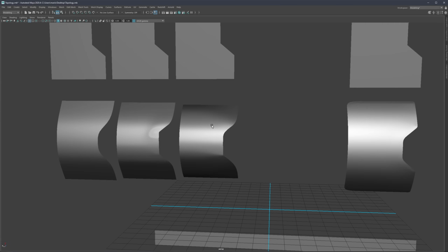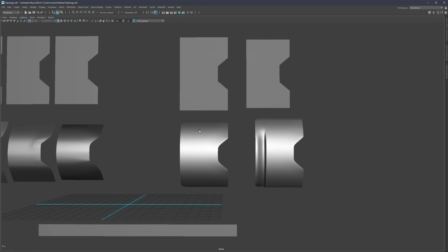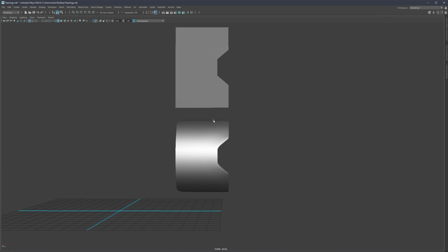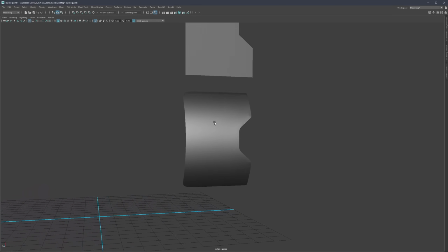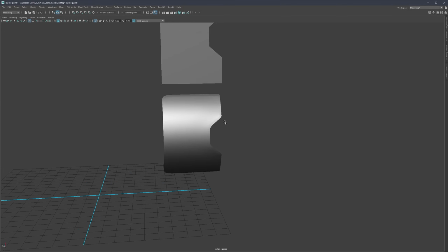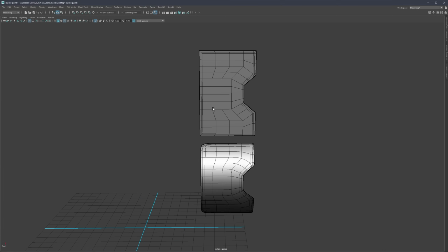So we can also think about how we can use all of what we learned from these mistakes to our advantage and create much more optimal topology, as shown here. Here we can see that the highlights are very, very stable, the corners are still relatively sharp, and we do not have any deformation. The important things to take away from this are three things: supportive loops, even spread, and redirection. These three key elements are something that we're going to constantly manipulate in our topology.